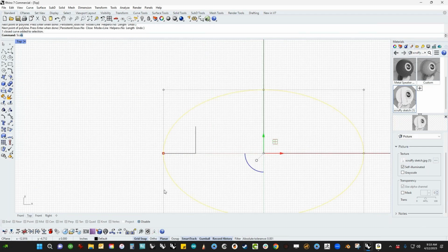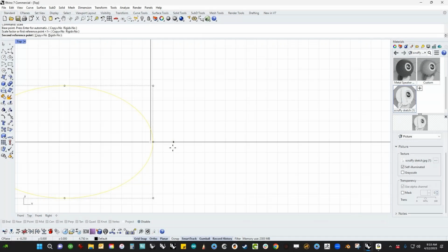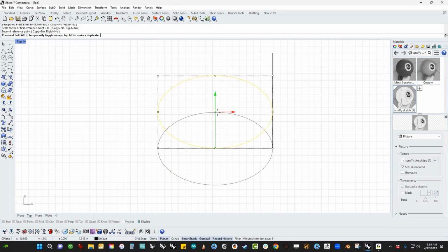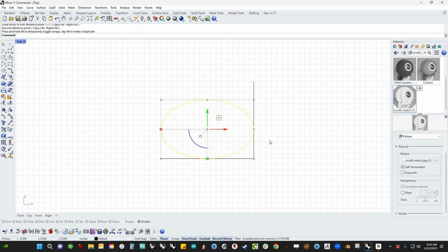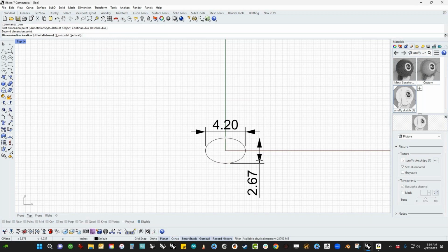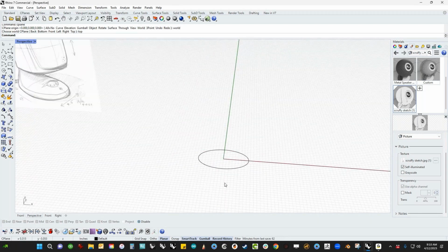And I'm just going to scale this here, somewhere close. Looks like my grid snaps on. Somewhere close to what I want to be. Like that. That's about what I'm looking for. Somewhere in that neighborhood. And let's move this from the center just to 0. And if we want, we can dimension this to look and see how we did. So that's about 4.2, about 267. I'm going to go with that because I like that proportion as opposed to what the dimensions are showing. The one thing that I will always say is make sure that the model is the rule, not the sketch.